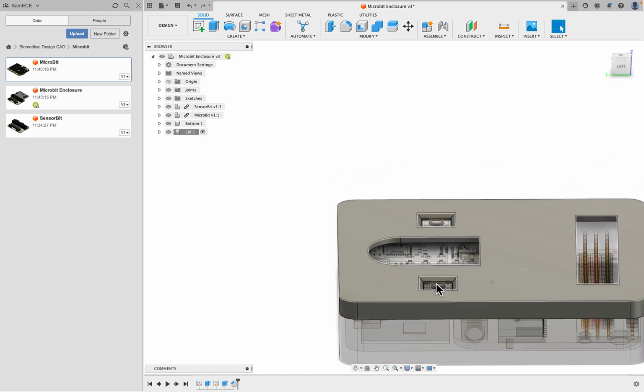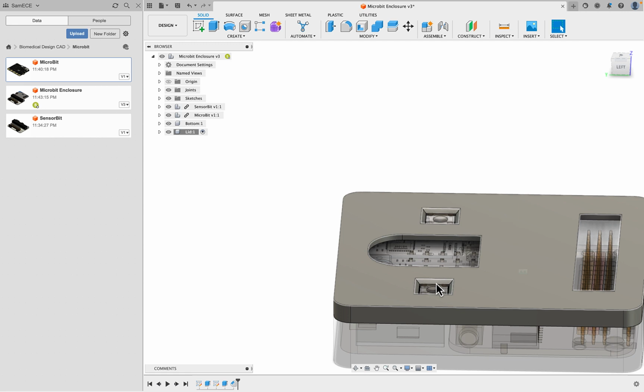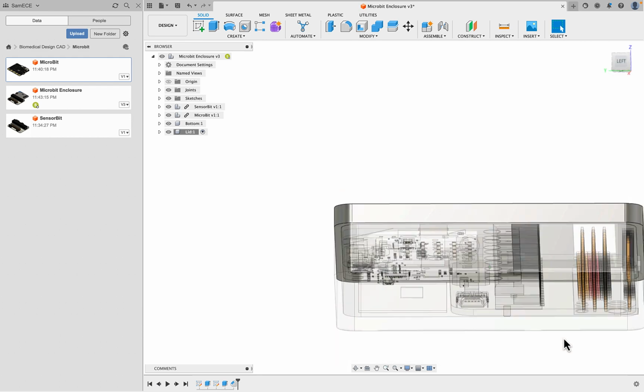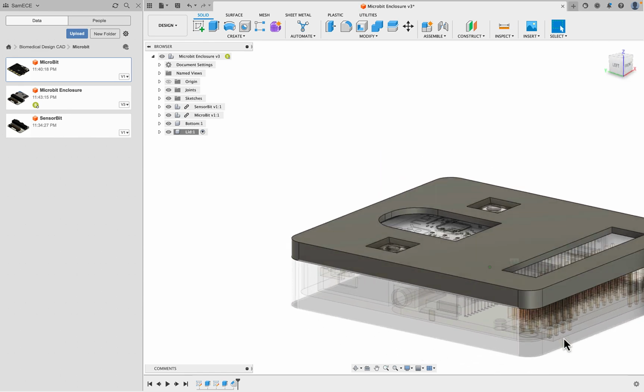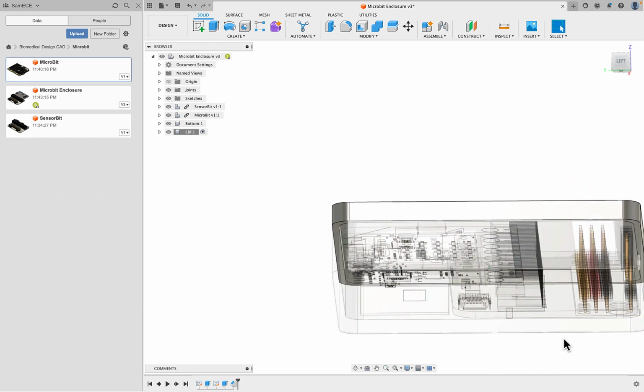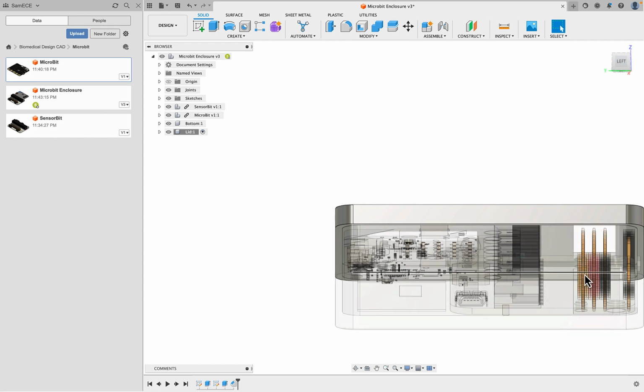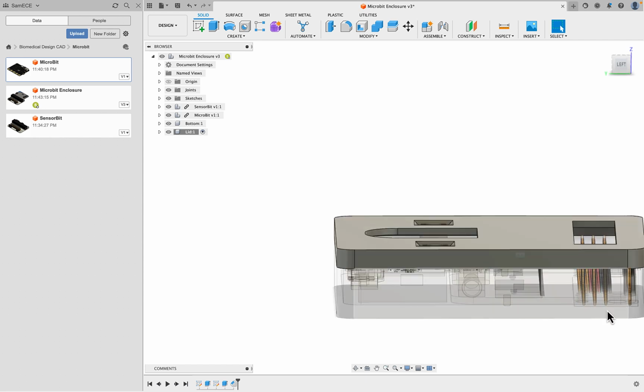The header part should probably have a box going around it, both in order to stabilize whatever you insert, but also to make sure that the bottom sensor bit part stays in place. As of now, it's just laying flat on the surface, so it can actually move up and down if you take your entire enclosure and shake it. So let's just do an extrusion of the inner part here, going down to the surface of the sensor bit board.